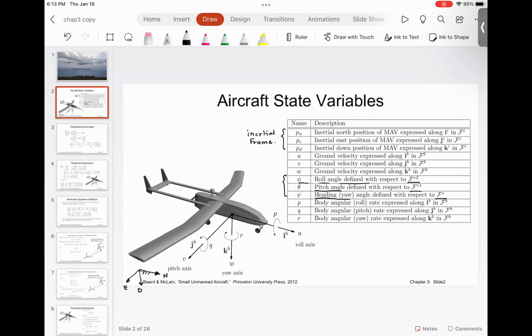If you look at the way we are going from the vehicle frame, from the vehicle frame we go to the vehicle 1 frame by a rotation of yaw. After the vehicle 1 frame, you go to the vehicle 2 frame by a rotation of pitch. And then from the vehicle 2 frame, we go to the body frame after a roll rotation. Everyone understood this? We spent a lot of time on that.